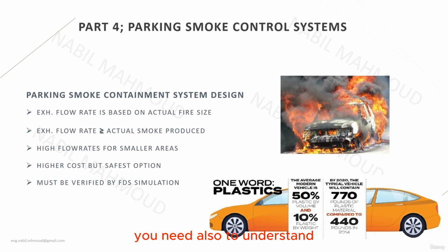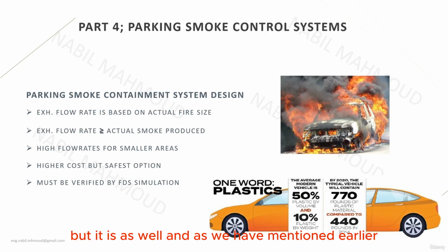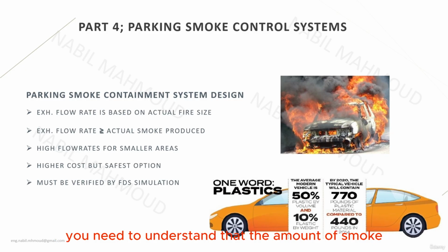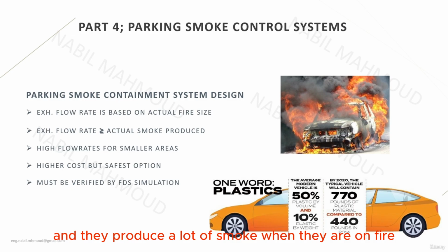You need also to understand that the smoke containment system usually has the higher cost or the highest cost, but it is as well, as we have mentioned earlier, the safest option that you will ever employ. And as a justification of the exhaust flow rate, which is relatively higher than the smoke management, you need to understand that the amount of smoke generated from a car fire is usually relatively large. This is due to the fact that the car is mostly made of plastics, and these plastics are very sooty and produce a lot of smoke when they are on fire.